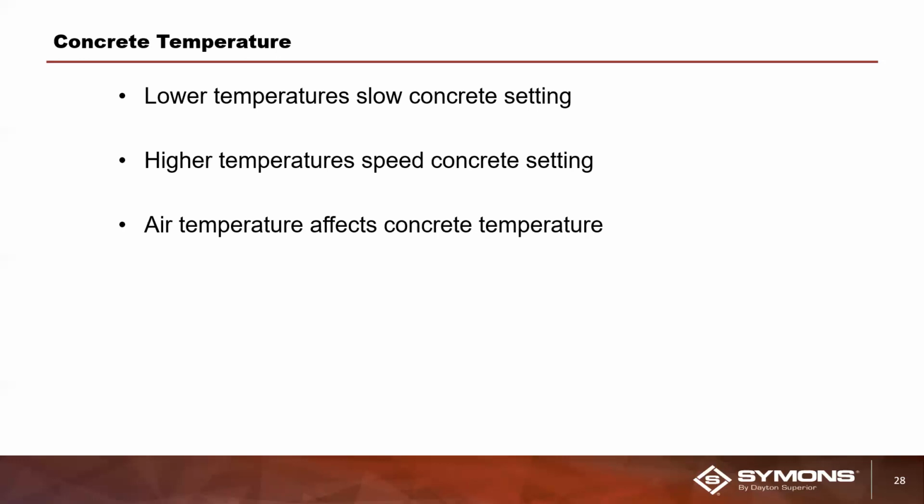Once again, this is the chemical reaction. So if it's a colder situation, it's going to take longer to set up. If it's warmer, it's going to speed it up, primarily because of the chemical reaction taking place here. It's going to be much easier to move along during that warmer weather. Air temperature does affect the concrete temperature.